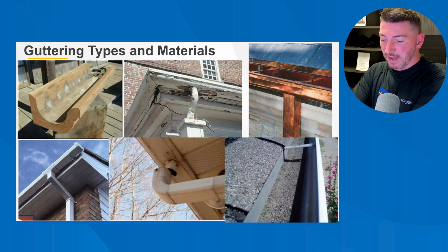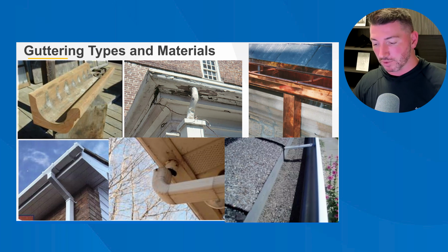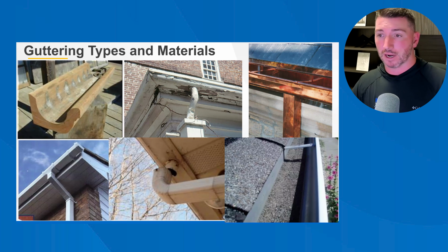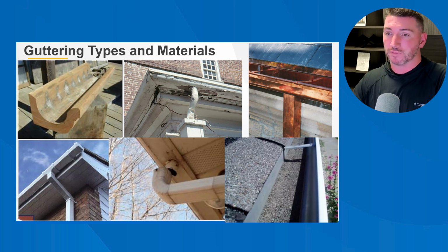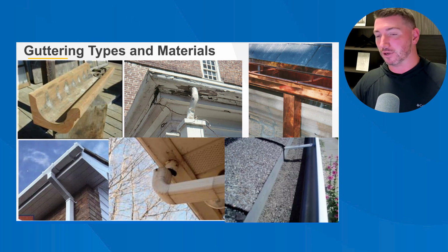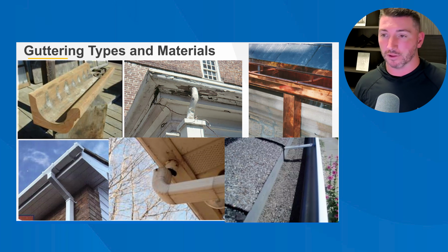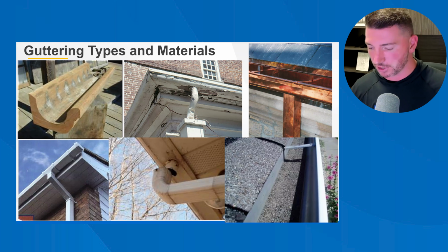Is the guttering securely fastened to the building? And again, you can't always readily see whether or not it's fastened to the rafter tails. If there's a way for you to see that, I would recommend calling that out, because if it's just screwed through trim's 3/4 inch board, and when you've punctured it with a fastener, now you've kind of broken the finish of the board. And if water's sneaking in behind that gutter, you're going to rot out that board, which might be true anyway, but if the screw penetrates all the way into the rafter tail, that gutter's still going to be secure. Are there any brackets missing?